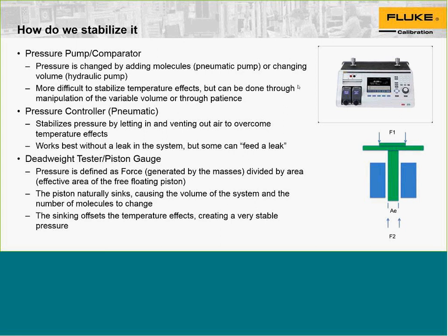When temperature effects are in play, there's inherently going to be some oscillation or some instability in the pressure, just because the pressure controller is looking for the pressure to change, and then it's making a change to the number of molecules to offset that. So you see some movement around the pressure, but with a well-tuned pressure controller and a good system, that will be insignificant in your calibration.